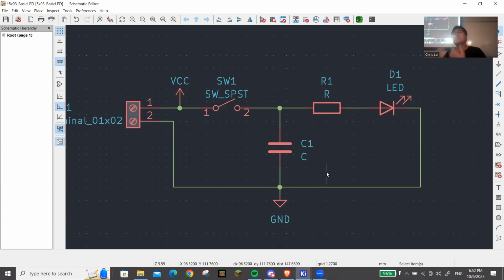But in order to make this more visible to others, you kind of have to name your components, right? Because let's say this resistor here doesn't actually have a value. If you were at the previous circuit analysis workshop, we instructed you to change the value of this resistance, right? And it had an actual effect on the simulation. However, in this situation, if you change the value of this resistor, the user or whoever's putting this PCB together doesn't actually have to follow it. So this can be an abstract value. For example, I'm going to put in 10K for this resistance.